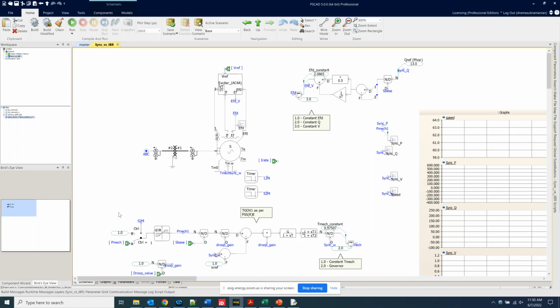Will that machine still be grid forming? Yeah. Why? It's like a voltage source behind your feeding. So if the grid voltage dropped, more reactive power would naturally flow out of the machine, and so it will remain stable as short circuit strength reduces. Maybe up to a point. I don't know. Okay, so let's see what happens.